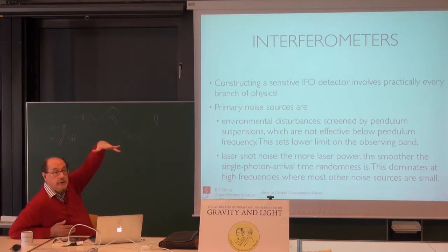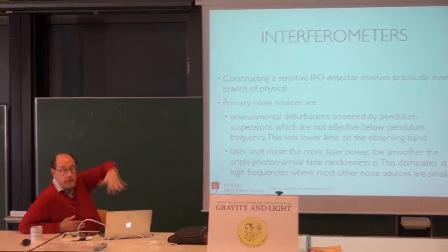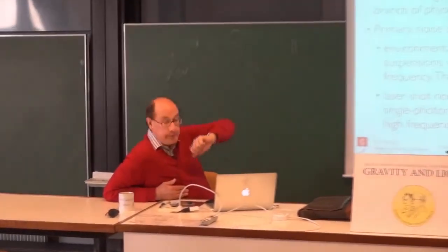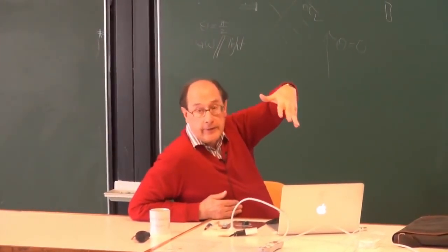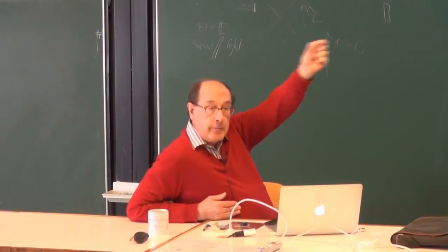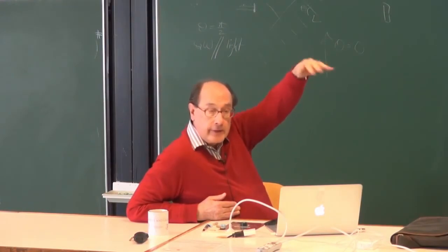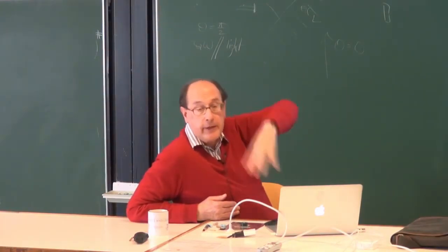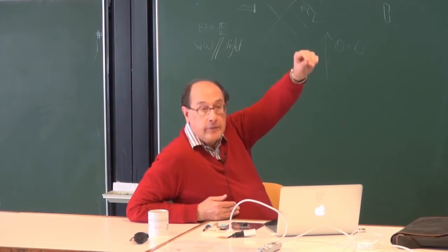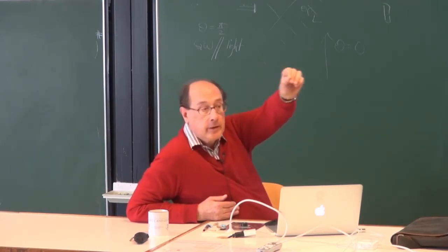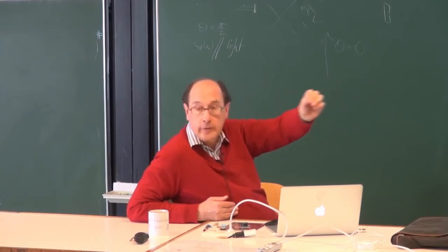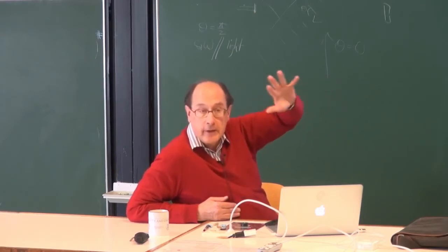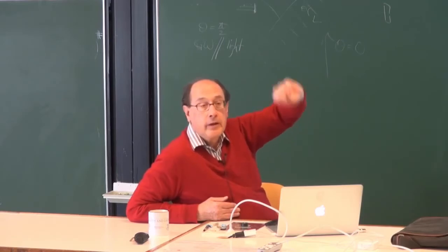So we hang the mirrors from maybe a meter or more of suspension, and you know with a pendulum that it's a mechanical filter: if you wiggle the top of a pendulum at a very high frequency compared to the pendulum frequency, then the pendulum hardly moves at all. If you move the top of the pendulum at a low frequency compared to the pendulum frequency, then the pendulum just follows along with your motion. So it's a low-pass mechanical filter.